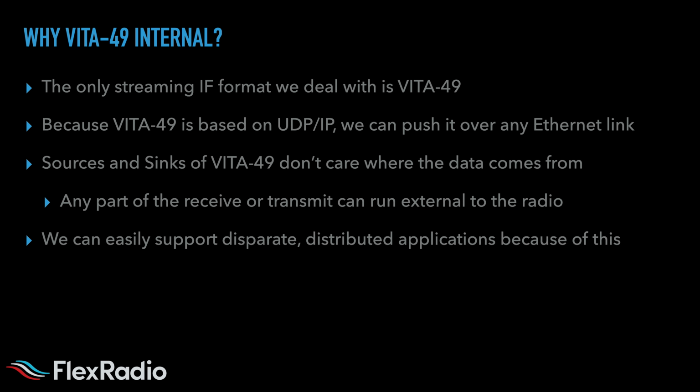So why do we do that? It is the only streaming IF format that we deal with inside the radio, and one of the key reasons we use this is, since VITA-49's definition is that it's based on UDP-IP, which is an internet protocol that's been around for 30 or 40 years, we can push this data over any Ethernet link. So this allows us to use it internally in the radio through our Ethernet switch, outside the radio through the Ethernet switch or Wi-Fi access port in your house, or send the data clear across the world using SmartLink to connect to your radio remotely. So it gives us a common way to send data around.